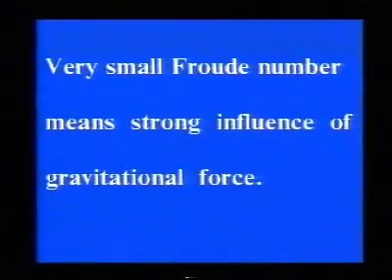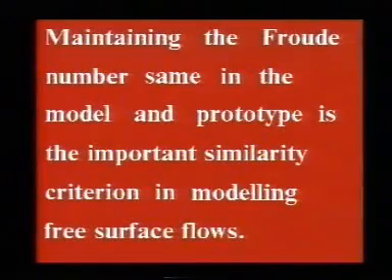Very small Froude number means strong influence of gravitational force. Maintaining the Froude number same in the model and prototype is the important similarity criterion in modeling free surface flows.